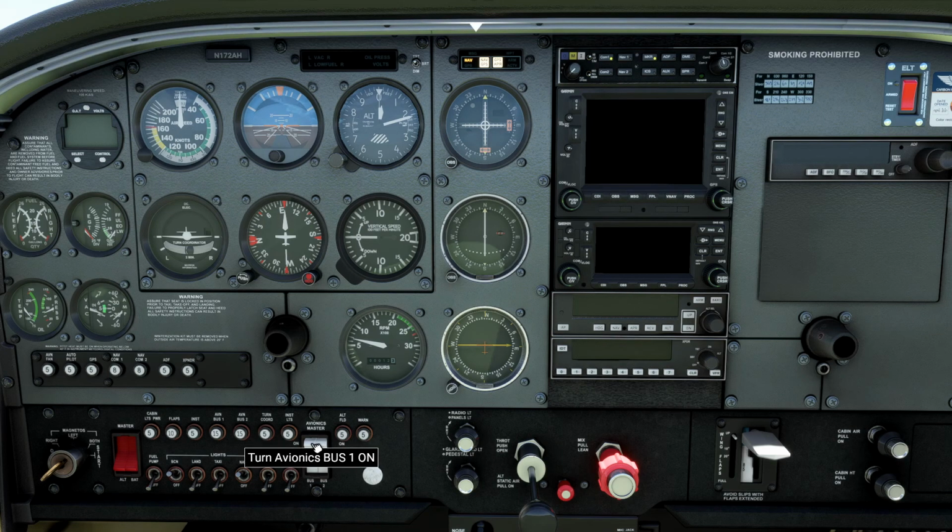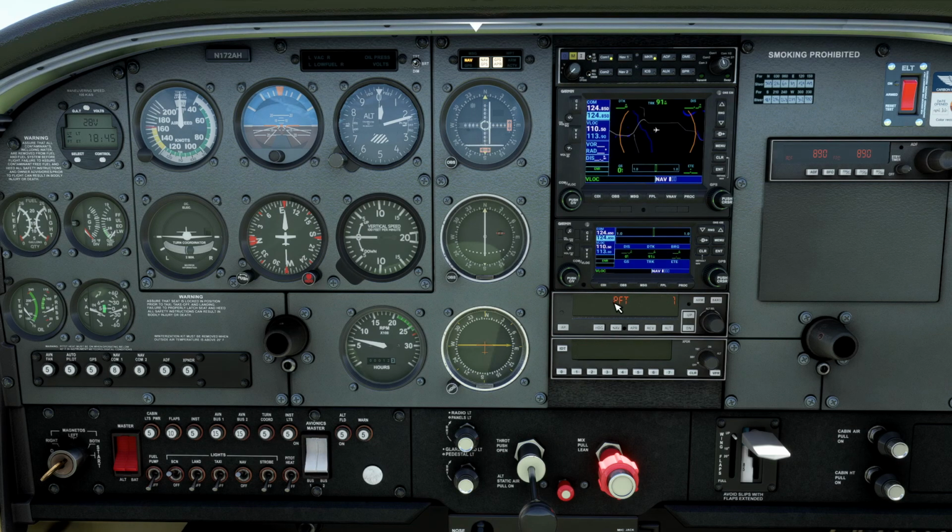Let's go ahead and power it up and see what that self-test looks like. You can see it on the display, it shows PFT, and then it has a number over here, and that counts up to 5. Once it gets to 5, it lights up the entire display. All the annunciators are lit up, and then it will stay like that for just a couple of seconds, and it'll sound the autopilot disconnect tone. And then once that tone sounds, it'll show a 0 over here on the altitude pre-select window, and the altitude alert will be on, and we know it's ready to use. There is the autopilot disconnect tone, 0 feet on the altitude pre-select display, and then the alerter is on.